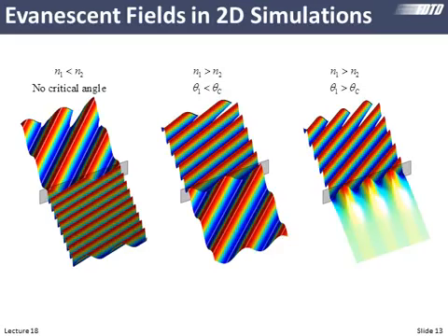We talked a bit about evanescent fields, and from this perspective of total internal reflection, here's one way that we can cause an evanescent field. If we have a waveguide, the field outside the guide will be evanescent. So it's a field that's not going anywhere. This evanescent field is not pushing power in the vertical direction towards our boundaries. It is pushing power, in this case left and right, but it's not pushing power away. But we definitely have these evanescent fields. And so resonant devices can produce evanescent fields, waveguides can produce evanescent fields, cutoff at an interface can produce evanescent fields. There are lots of mechanisms that can produce these evanescent fields. And we already know we don't want the evanescent fields to touch our PMLs.